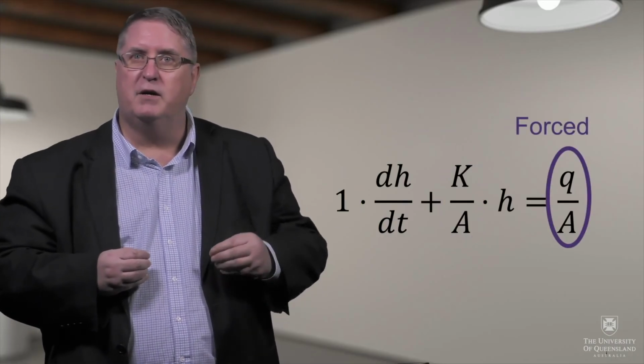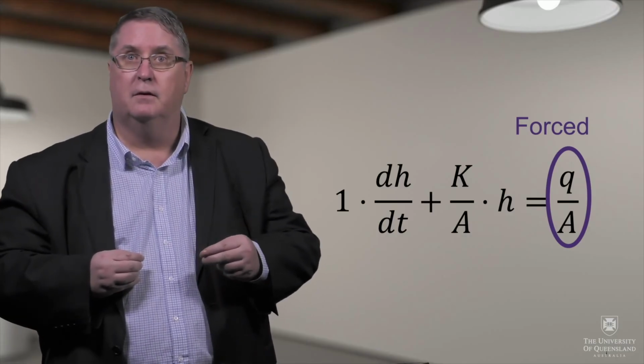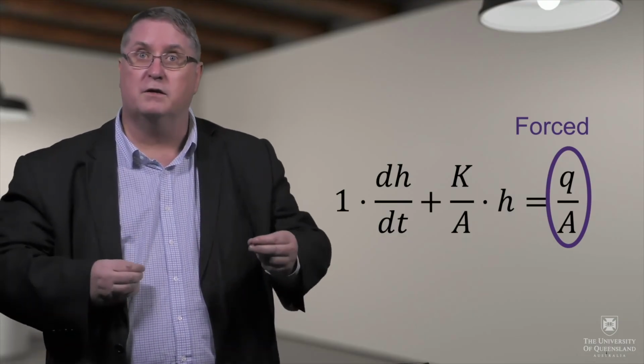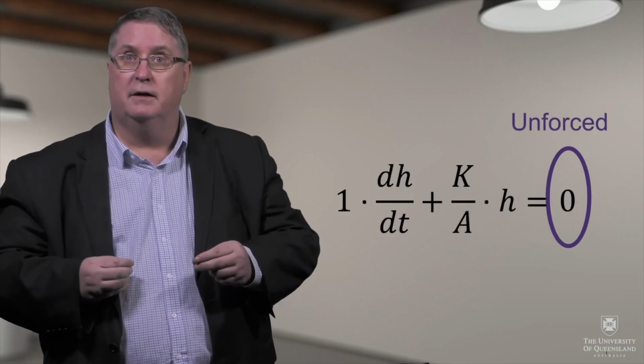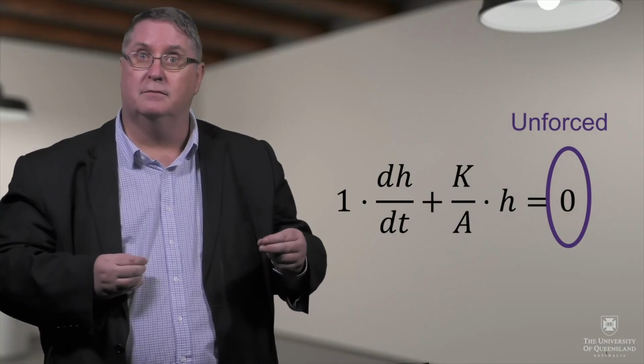It's forced because it's driven by an input, here the inflow denoted by q. The response of h to a given input q is called the forced response. If we set the inflow to 0, the equation becomes unforced. An unforced system will still have a response that varies with time if it has non-zero initial conditions. For example, a container with a hole in it will empty if it contains water. The response of a system due to its initial conditions is called the free response.